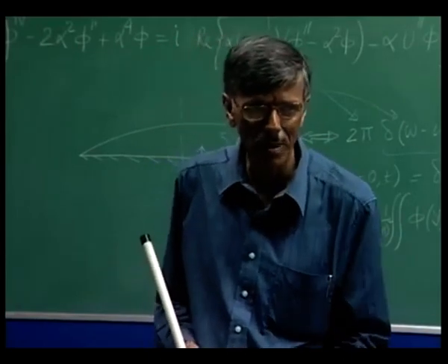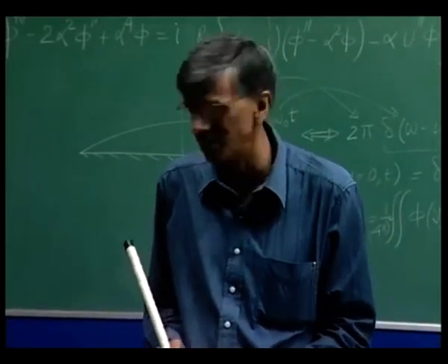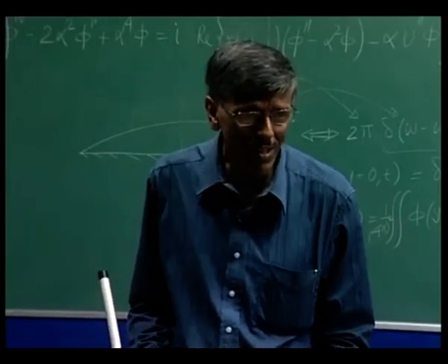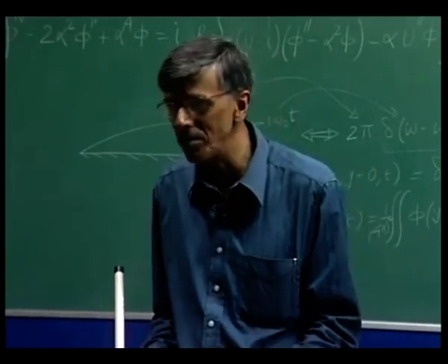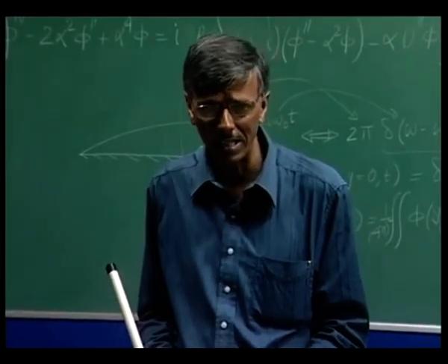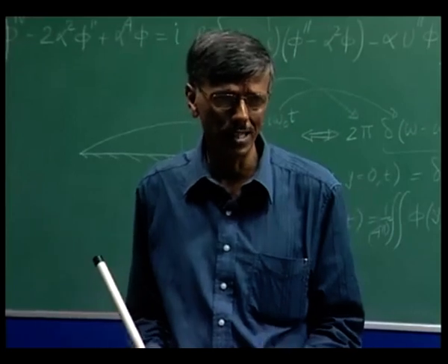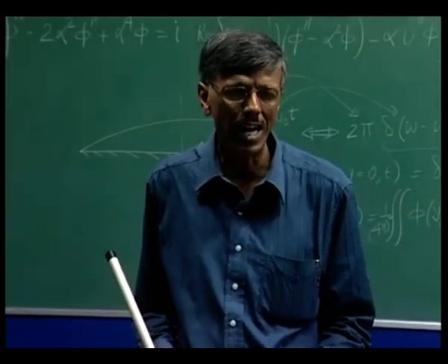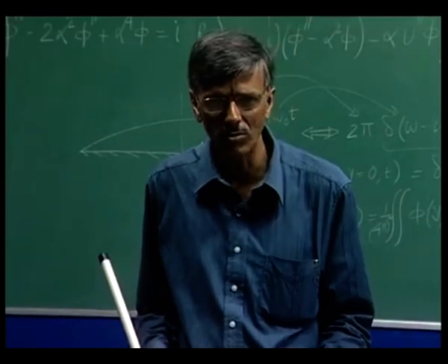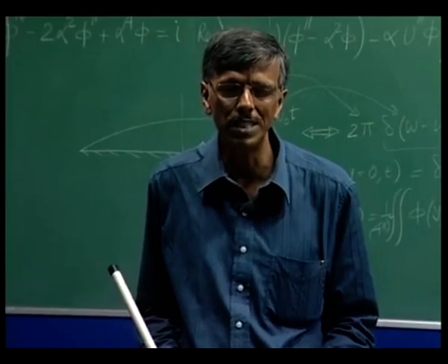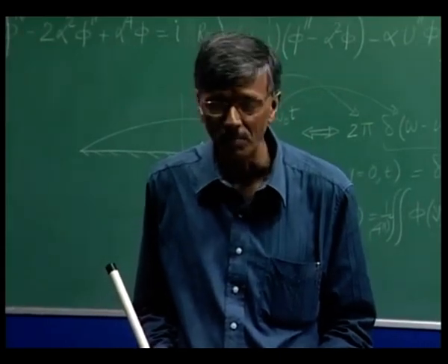If I can stop the background of that particular class of disturbance where the dispersion relation resides, I won't have that response. And that's why people have gone ahead and obtained Re critical for flow past a cylinder to a very, very large value. That has gone as close to as 100,000, while Reynolds obtained it around 12,830.